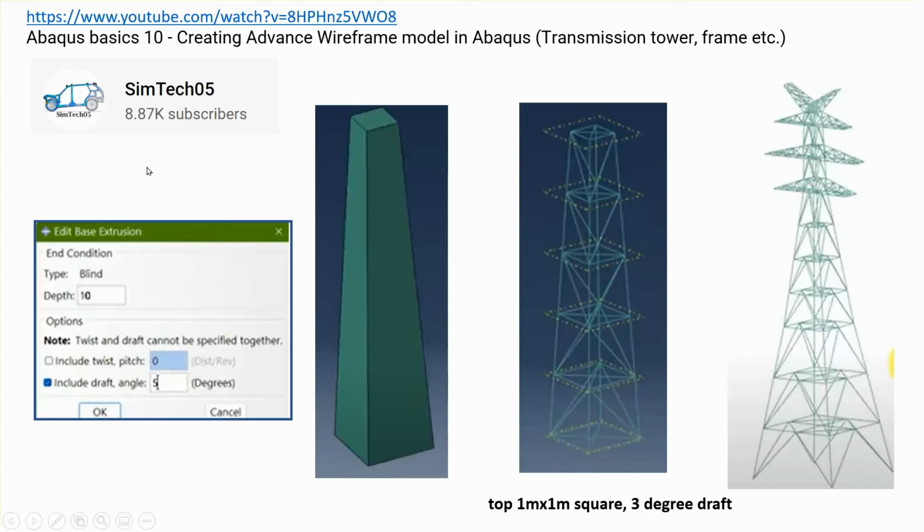Now, I will do the same thing, except that I will not cut this into, let's say, here you have basically 1, 2, 3, 4, 5 bays. So I'm going to do only, let's say, 3 bays, okay? The way this is done is that the top is generated, and then this drafted pad is created as a solid, and then split with these reference planes, so that you get, in my case, 3 layers, in his case, 5 layers, okay?